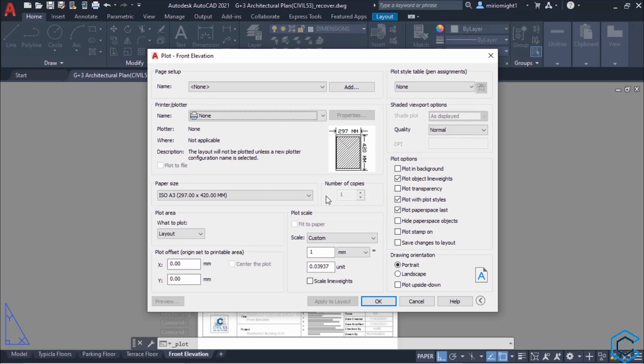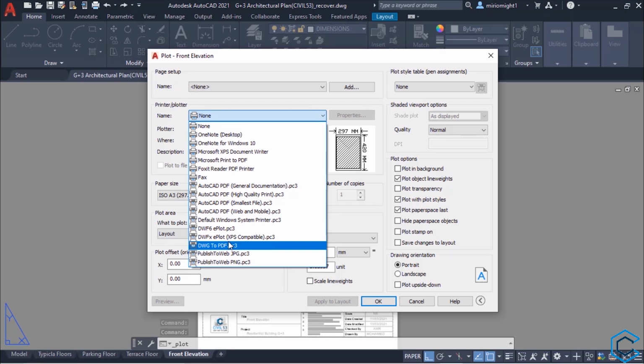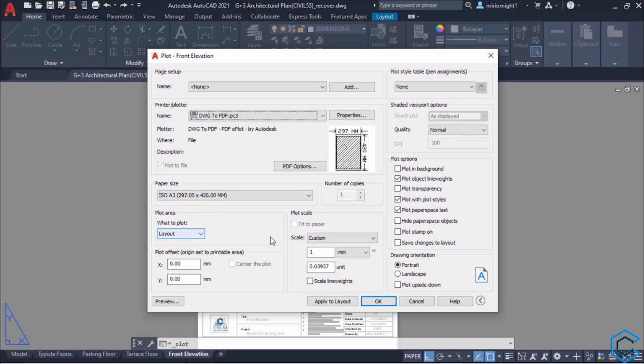So, keeping in mind that scaling is only done in model space to print a large plan into small size paper, by now it should be clear that in layout space we never have to change scale value. It will always be 1:1 because virtual paper layout size and real paper size is same. The scale value concept will come into picture only if we try to print the plan directly from the model space. Now we are on our layout tab and we have selected the scale 1:1.